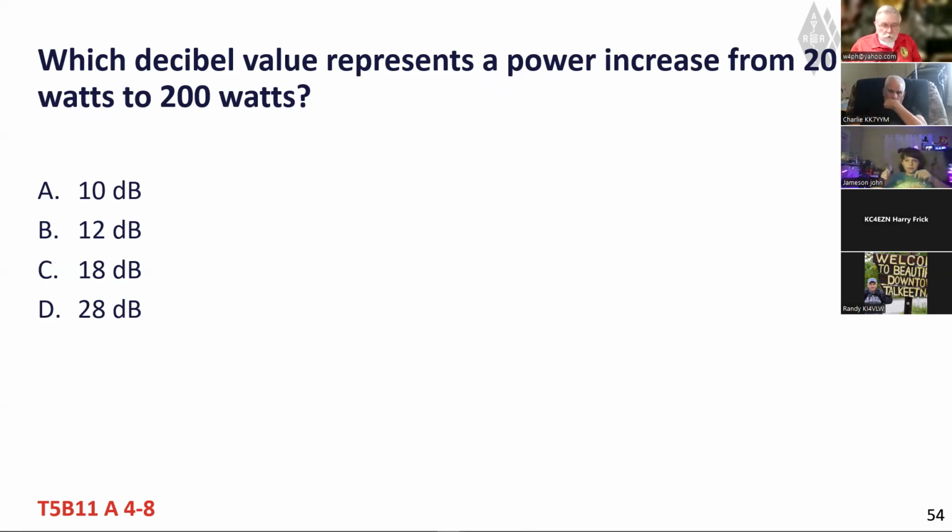So if you're going to raise something times 4, you would say 3 dB plus 3 dB is 6 dB, which is equal to doubling the power twice. Every time you double the power, it's 3 dB. Now, if you're used to using logarithms, you can get everything in between all that when you look at the logarithmic number of what you're working with.